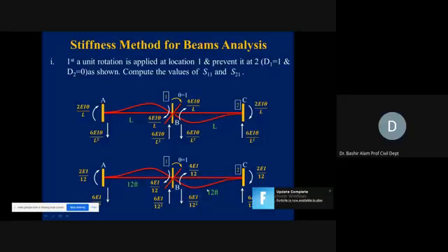Now this corresponding span you will have to include. At the far end, which is C, 2EI divided by L, half of MB. And again, the unbalanced moment is in the clockwise direction, so the balancing moment will be in the counterclockwise direction. And that is how we get 6EI divided by 12 square. Again, this 12 is the BC span.